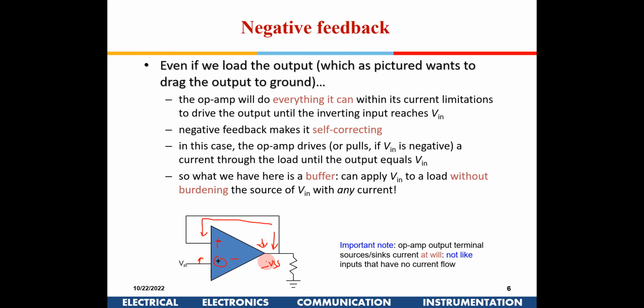But we do use these as comparators, especially in ADCs, where we compare an analog input with some V reference. So we use it in open loop configuration. Comparators are made with open loop; otherwise, amplifiers generally use negative feedback.